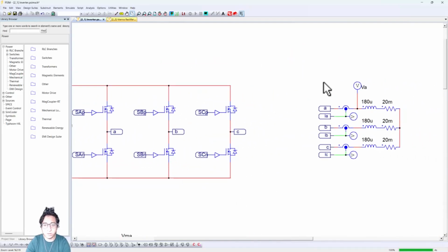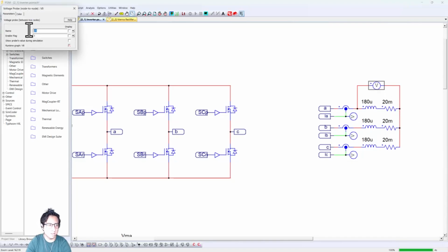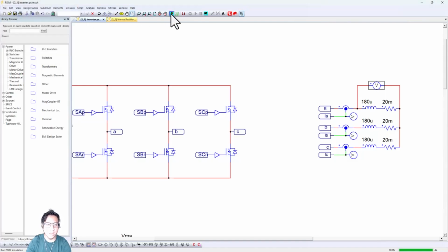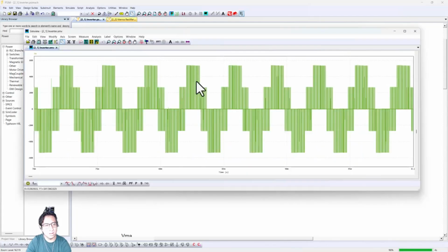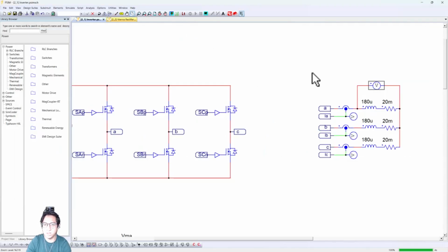The correct way of doing this would be to use a 2-point probe, like this one. We grab it from the bottom side ribbon, and we can easily connect this way. And next time we simulate this, our measurement is going to be correct. Okay, that now makes complete sense. Additionally, we could just place this sensor here, right?